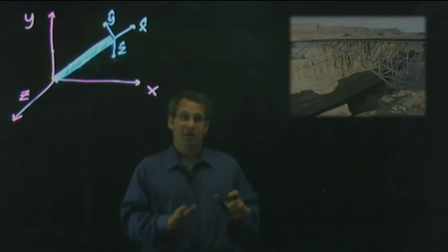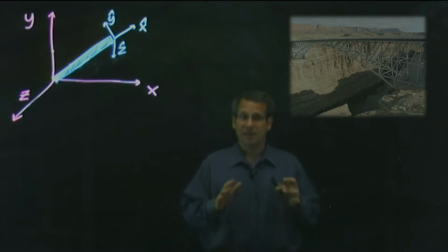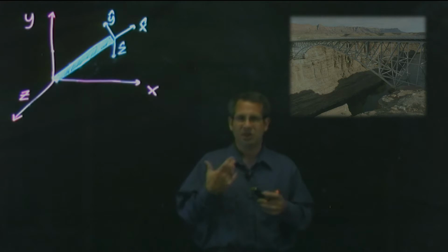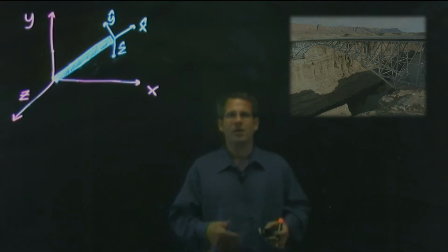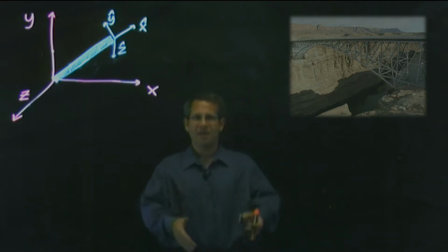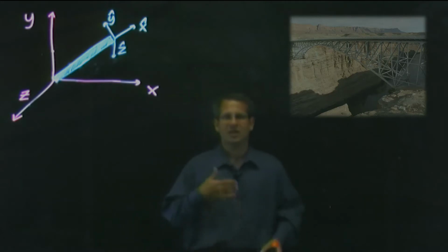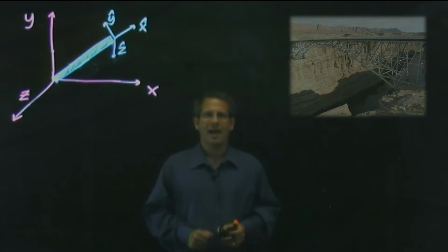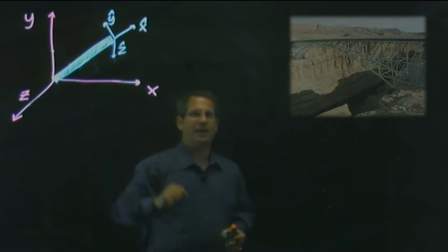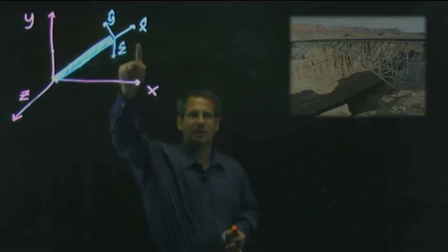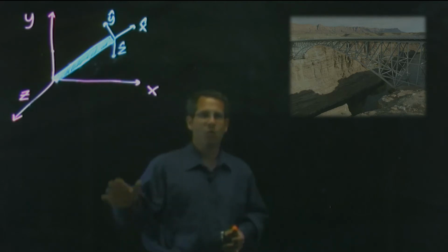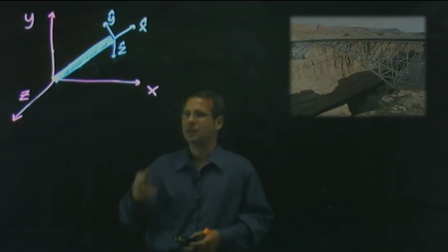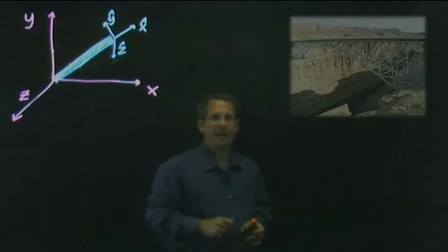But this week, trusses in 3 dimensions is going to seem very similar to what we did last week in 2 dimensions. So we'll go a little bit quicker since we're essentially going over the same methodology we did last week. Again, we're just adding a 3rd dimension to it. For each bar element in our truss, we'll have a local coordinate system, x hat, y hat, and z hat. We'll form a global coordinate system for our convenience to analyze the entire truss, x, y, and z.